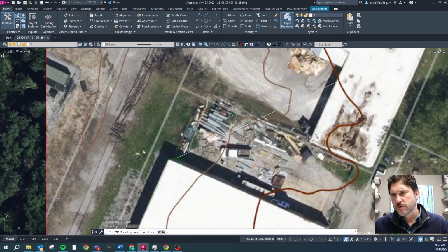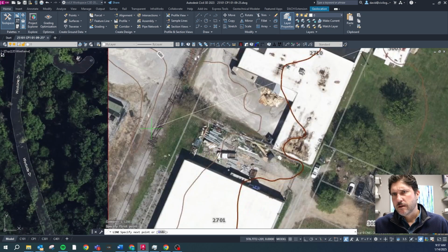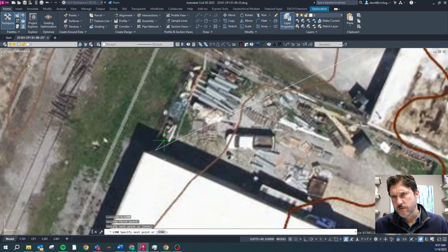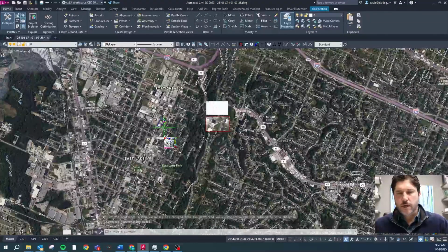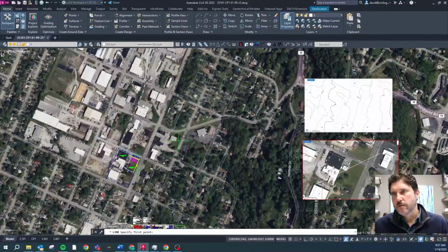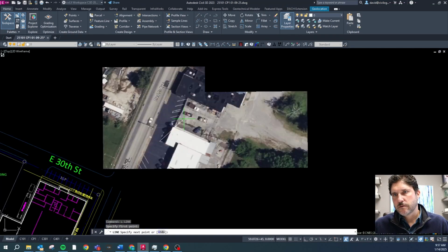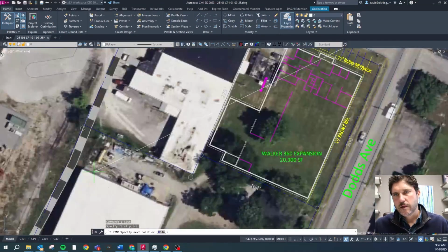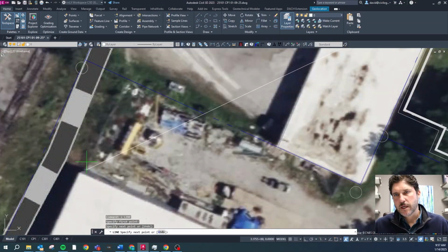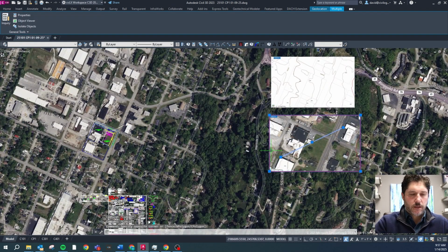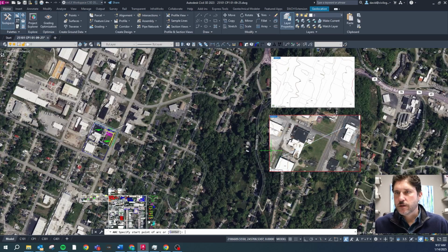We could potentially use the corner of that building there. Let's do that. Let's use the corner of that building, and then we'll do that in the project model. So we've got the tip of this line there, and then that bottom corner of the building there. And then we're going to use the align command, so I'll grab these two things, AL, enter. Start point is this one, and that goes to there.